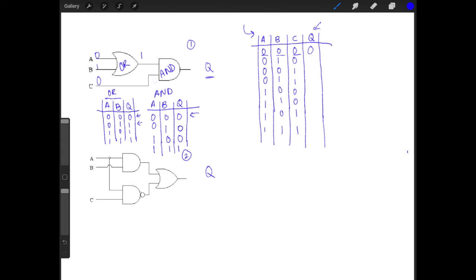And then our AND gate will have an input of 1 and an input of 0. So look at our truth table again. If A is 1 and B is 0, then our output will be 0. So then Q for this diagram will be 0 for this second situation. So now we'll be repeating this process for all the other situations. So I'll write that out really quickly, and then you can follow along.